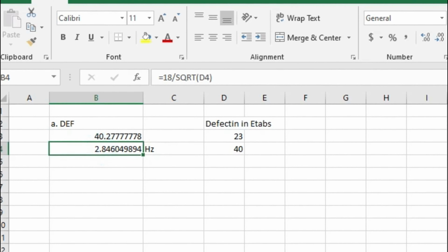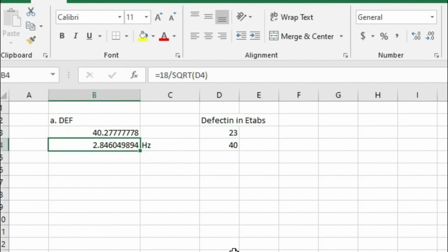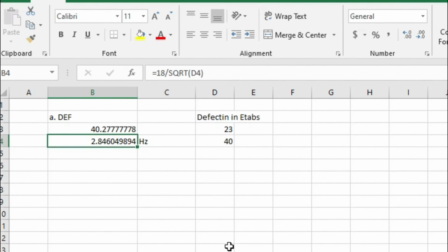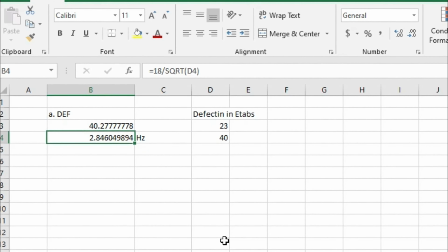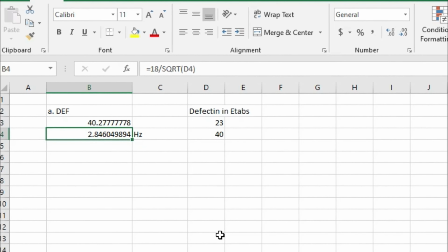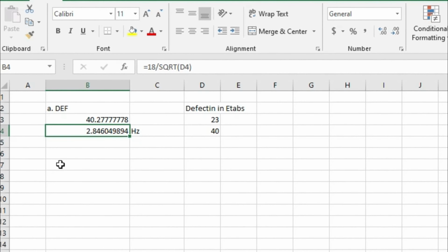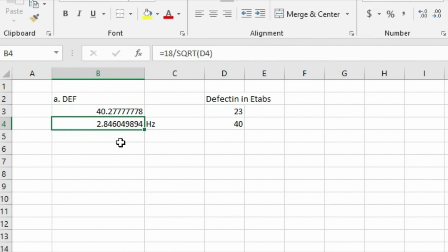So the floor vibration is unacceptable. It's lower than the lower bound floor vibration in the range 4 Hz to 8 Hz, generally 4 Hz to 8 Hz or 4 Hz to 10 Hz. To prevent resonance on the structure, it is not acceptable.